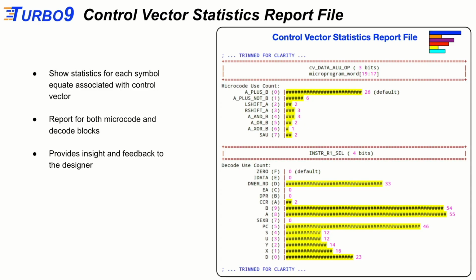So what are we looking at here? So here's the data ALU operation. You can see I do a lot of adding. So A plus B. And this is taking the entire instruction set and looking at it at that level. A lot of the time you're just passing stuff through the ALU, so you'll just do A plus 0, right, just to pass things through. So you use the add function there. There is no pass function on the ALU. The ALU is also obviously capable of A plus not B for subtraction, left shift A, left shift, right shift, and then some logical functions: and, or, XOR.